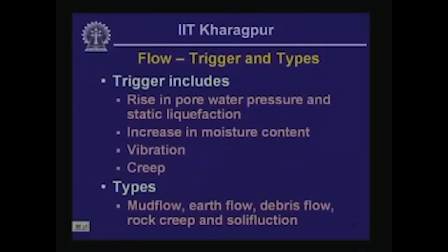Okay, now how could flow slides be triggered? Triggering of flow slide could be due to rise in pore water pressure and static liquefaction. As you recall, liquefaction is the phenomenon in which, because of an increase of pore water pressure, the effective stress becomes almost zero, and that could be triggered even without an earthquake. It could be triggered under a static scenario because of rise of pore water pressure.